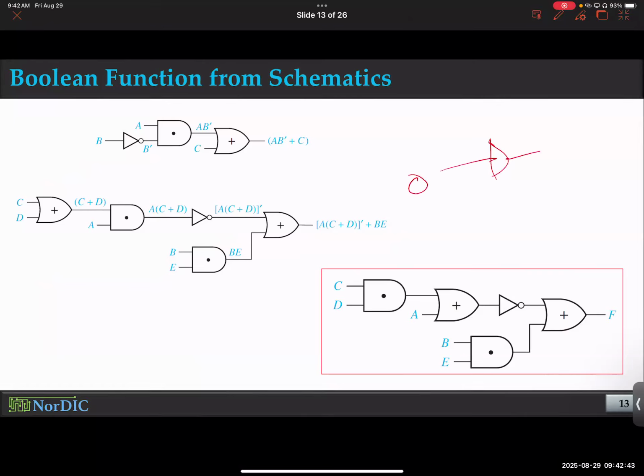It spits out the same thing, 0, 0, 1, 1. So input and output are exactly the same. Why would you even use them then? They're used to regenerate signal. So when you have a pipeline of circuit, signals degrade. So initially, if you provide 5 volt, you end up with 4.8, 4.5, 4.2. Gradually, as you go through the chain, the voltage levels will degrade. So you insert a buffer, and the buffer takes it all the way back to 5. So buffers regenerate. And that's literally a lecture in 433.